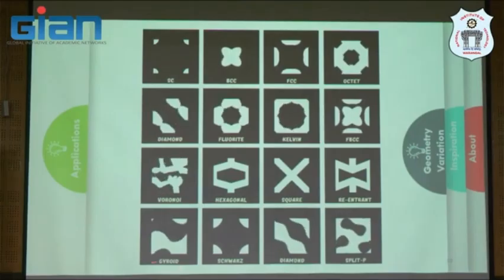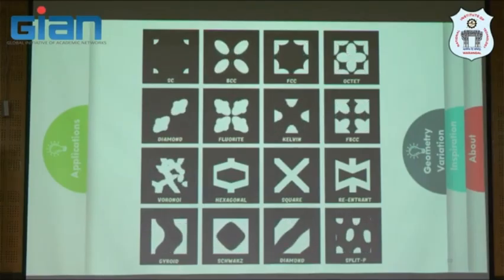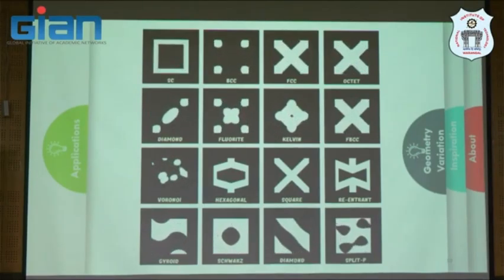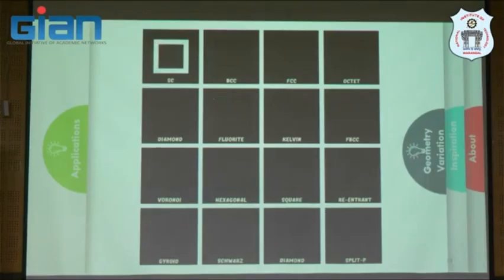Most of the people work on TPMS lattice structures only. The advantage of TPMS is that we can easily go for printing and all those things. In strut based ones there are some defects. The properties are good for TPMS with the same weight actually. So gyroid and these are the 4 TPMS lattice structures actually.